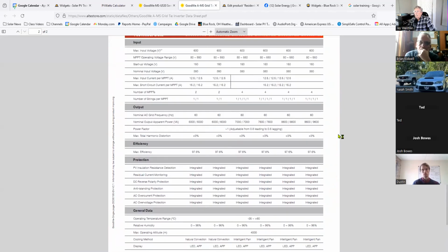Is that voltage? Volt amps. Apparent volt amps? Volt amps, yeah. And that's a little bit confusing because loads use power in terms of watts, but generators produce power in terms of volt amps. And of course, watts equals amps times volts. You would think they're the same thing, but they're not quite, because not every load uses power at 100%.